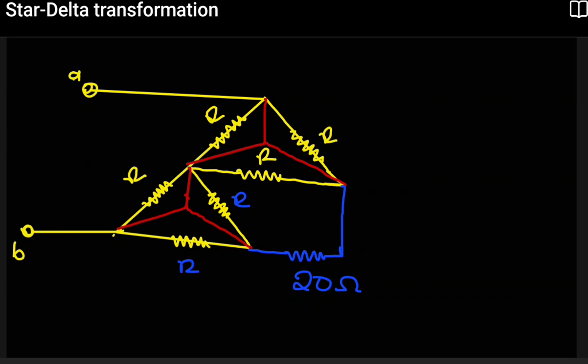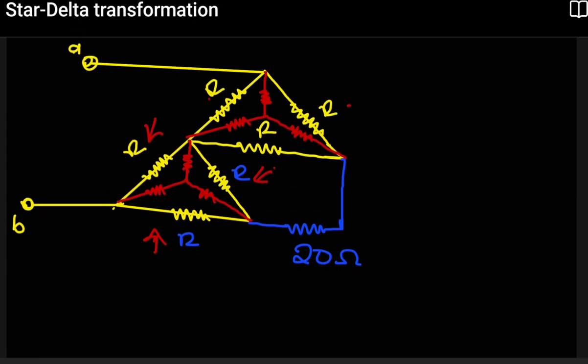The resistor on this side will be the same value as this one, because it's the same value R everywhere. Because of that, we're going to see those similarities. With that in mind, all we need is to resolve one delta transformation, transform it into a star, and then we'll know exactly what the others are going to be.